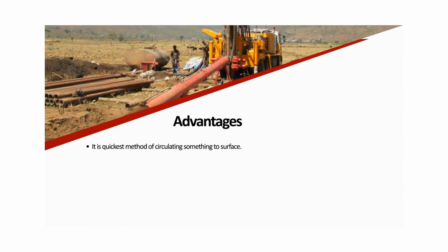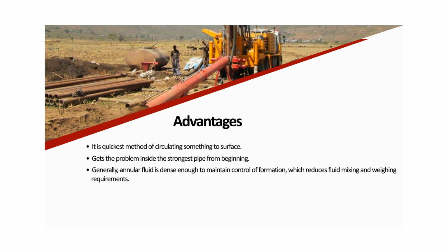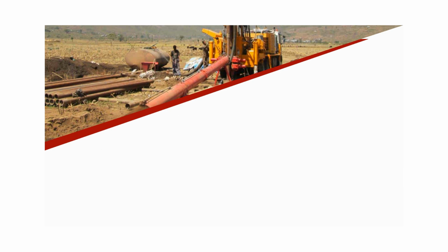Advantages. It is the quickest method of circulating something to surface. Gets the problem inside the strongest pipe from the beginning. Generally, annular fluid is dense enough to maintain control of the formation, which reduces fluid mixing and weighting requirements.